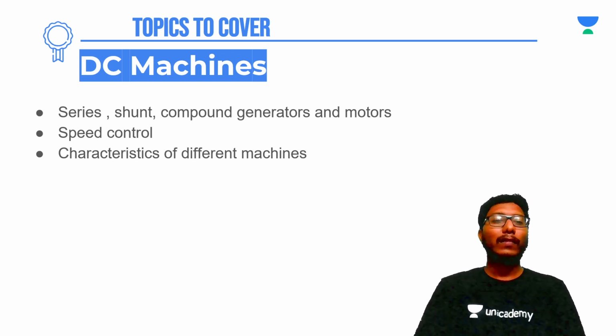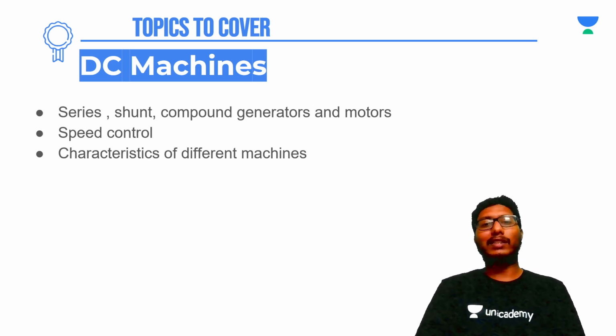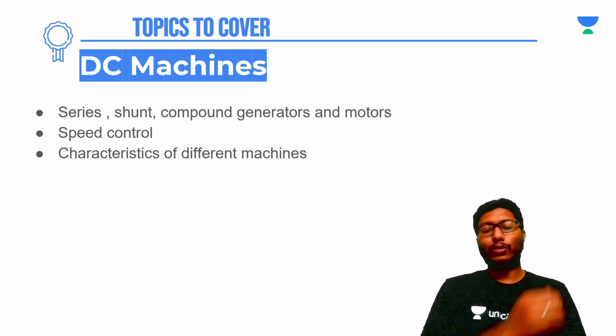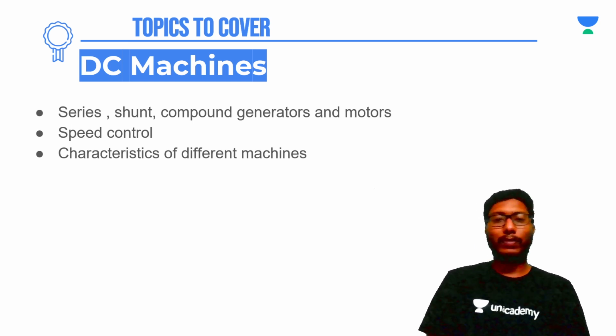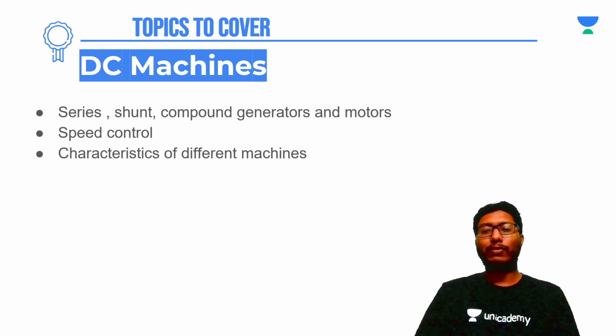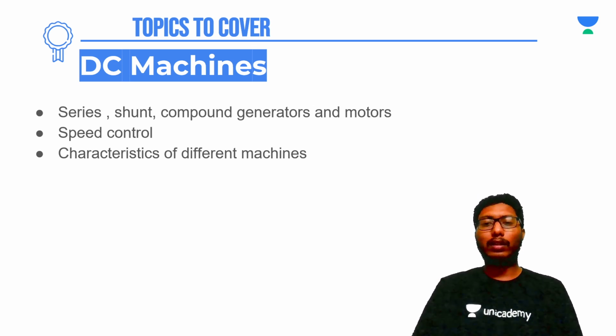generators. And one more important thing is knowing the power flow. In a generator, the armature supplies the power and it is distributed to the load and to the field as well. So you should be careful with current directions. Sometimes in the examination, the same machine will be used as generator and motor. You will be asked to find different currents that are supplied or currents at the load. If you know how the circuit looks like, and the type of generator is given, then you can have a good shot at solving the problem easily.